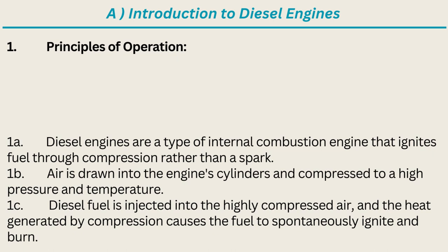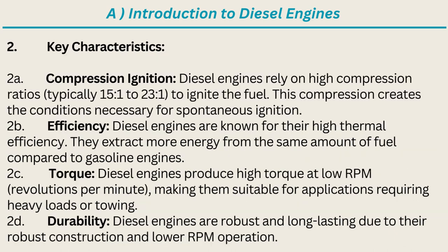Diesel engines are a type of internal combustion engine that ignites fuel through compression rather than a spark. 1b. Air is drawn into the engine's cylinders and compressed to a high pressure and temperature. 1c. Diesel fuel is injected into the highly compressed air, and the heat generated by compression causes the fuel to spontaneously ignite and burn.